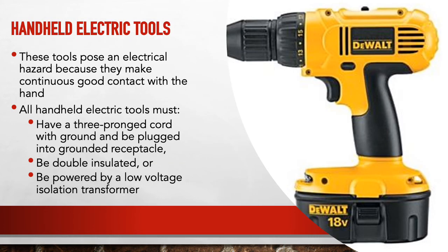So handheld electrical tools are typically going to have this. That's just going to be that separation. They need to have 3-pronged cords with grounded plugs to be grounded to the receptacle, be double insulated, or be powered by a low voltage isolation transformer. Once again, just another protective measure.